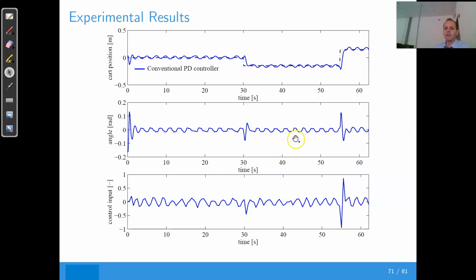But with a simple PID or PD controller, the control performances are very limited, because the system continuously oscillates around the reference. If you include a supervised controller, it means that the gains are not constant, but are modified according to the working conditions of the system.